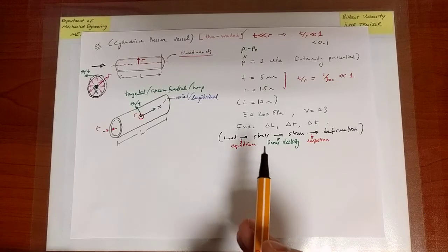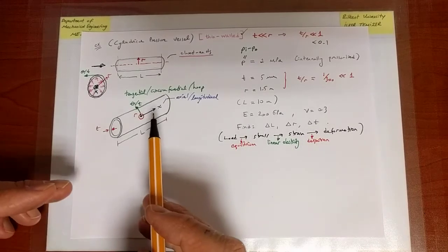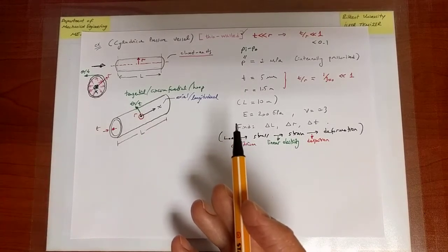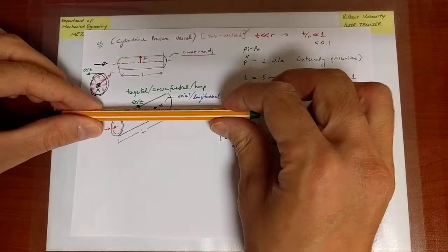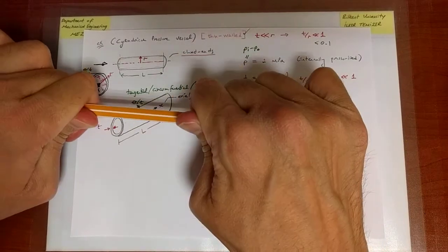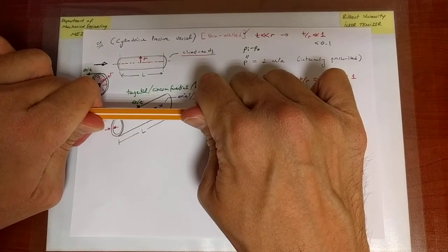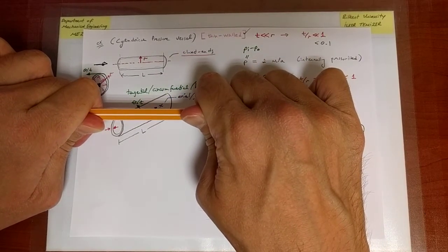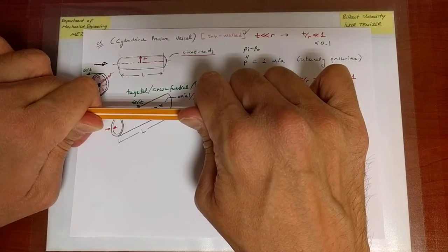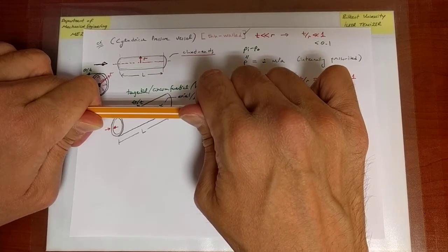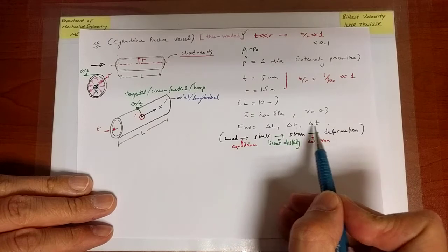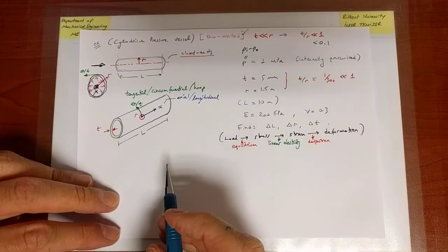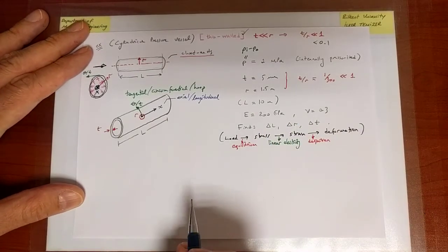Now, we're only going to be concerned with normal stresses and strains because in this problem, there are no shear-inducing forces. If I had taken this pressure vessel and tried to torque it, and in the future we're going to look at problems with such loading, then you would additionally have shear stresses. In some of the homework examples, you will have shear stresses. But presently, we will have only normal stresses and hence normal strains, and these changes in length are associated with normal stresses.